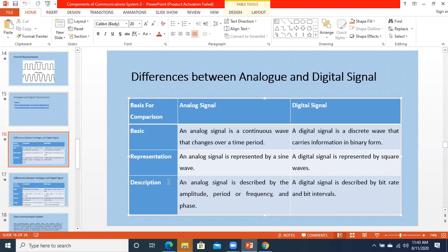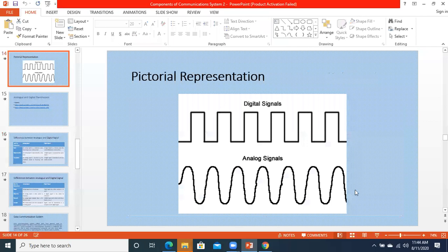When we talk about the analog signal, it has frequency, amplitude and period. These are all related to the analog wave. Amplitude means the distance between the mean position and the extreme position, and the period or frequency is how many cycles it covers in how much time. Just like analog current is measured at 220 volts, where 220 is the voltage and 50 hertz is its frequency. 50 hertz means it covers 50 cycles per second.